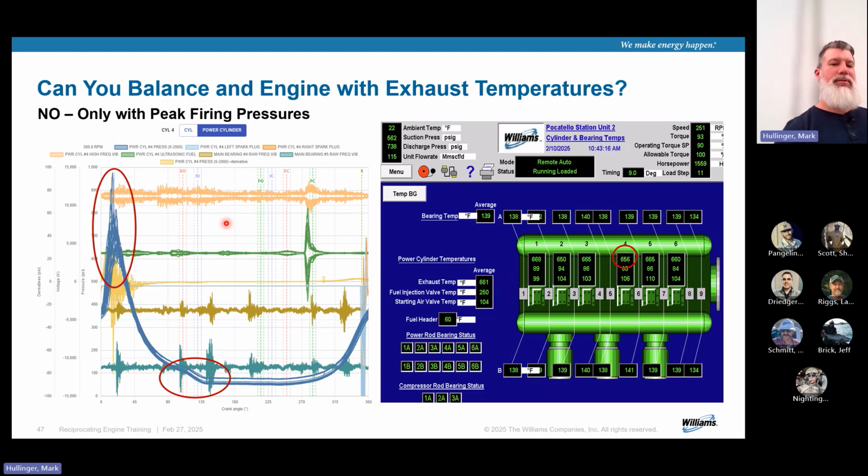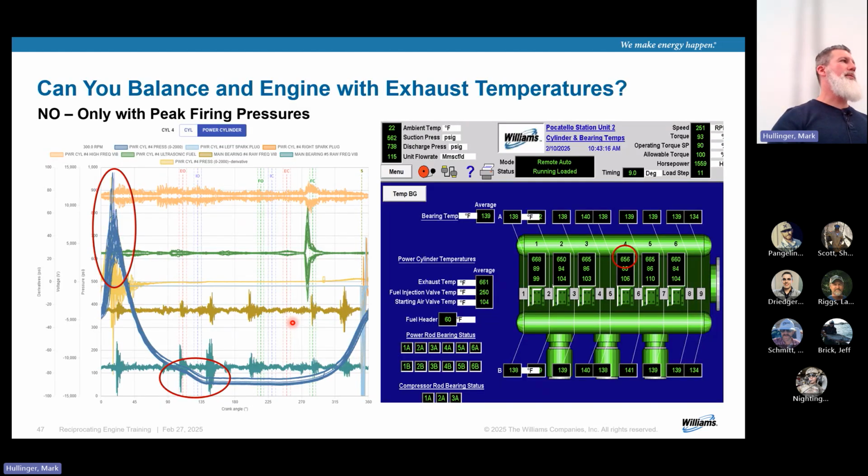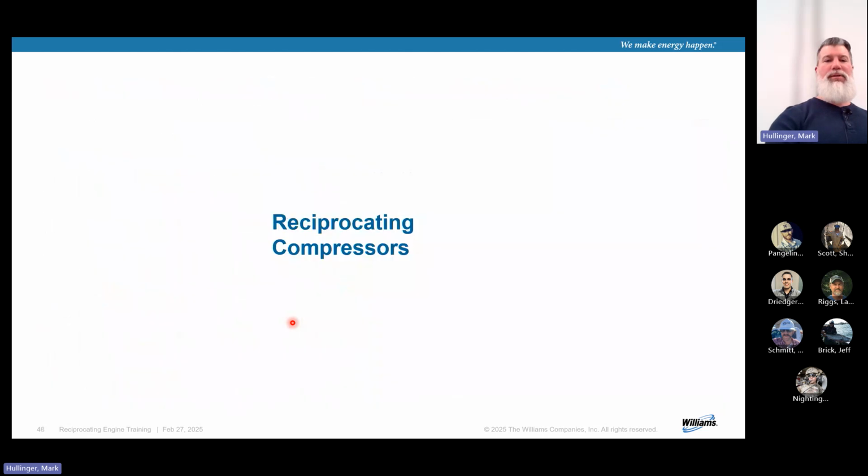Okay. So this was on the resonance. We diagnosed that. I think Cody went out there and he said, yeah, we got something wrong with that fuel valve, right? This also happened to be higher than the rest, this fuel valve closure. So there's 2 pieces of evidence right there. If I'm just using this, I don't get the answer, right? Okay, does that clear that up? Makes sense? Questions, comments? Okay, should we move on to compressors?